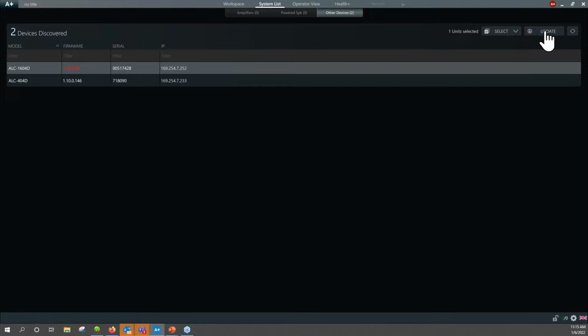Now, the thing is, when you're connected, talking to the server, okay, this firmware update will be available. So an internet connection is important when we're working in the field. We highly recommend when you're programming these amplifiers for the first time, do them in the shop when you have a secure internet connection, and we can get onto the server and download and do the updates. Trying to do this out in the field, tethering off a cell phone, if you're locked into an IP range or the IT guy's not letting you dial out or get in, that's an issue.